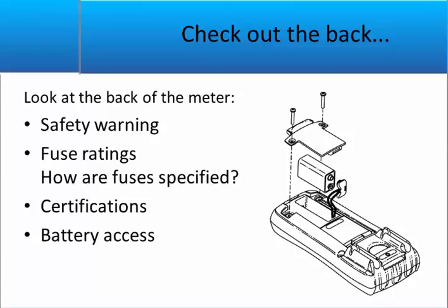fuse ratings, any type of certification, and make sure that you never operate the system without the back cover, because it exposes the user to the full voltage of the applied voltage.